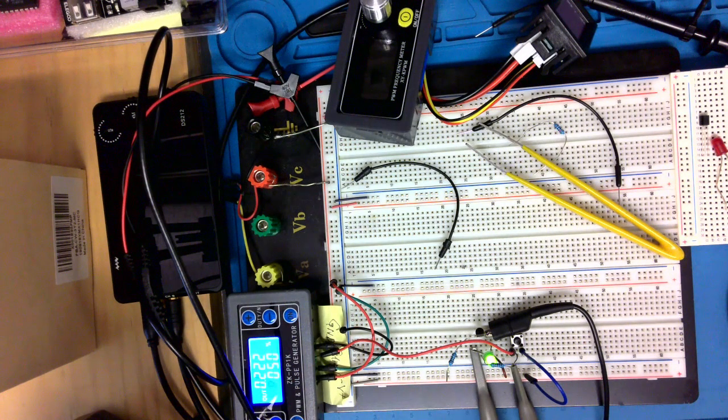I don't have a good MOS device here, so I cannot make comparisons, but MOS is also operated pretty much the same way in NMOS configuration. CMOS is going to be different. You see the rise and fall time becomes an issue because the output load is a capacitive load, and you have to charge up a capacitor and discharge a capacitor. Okay, that's it.